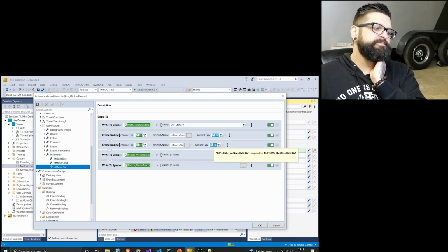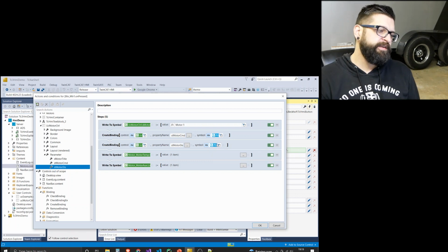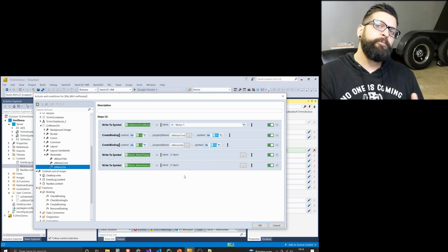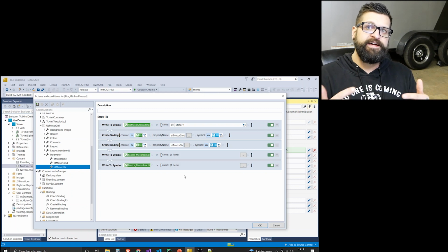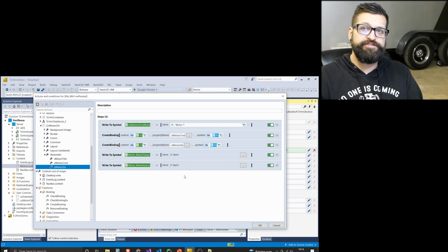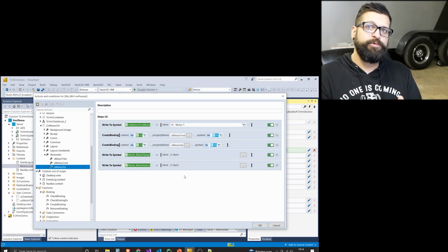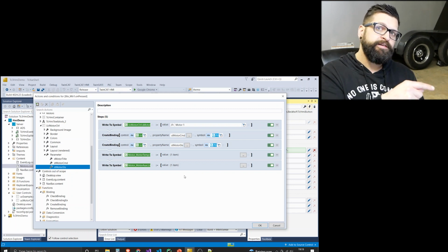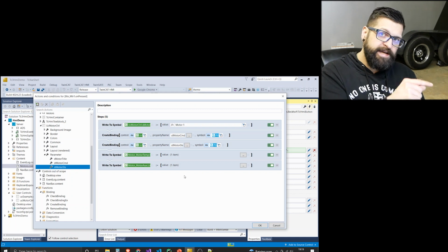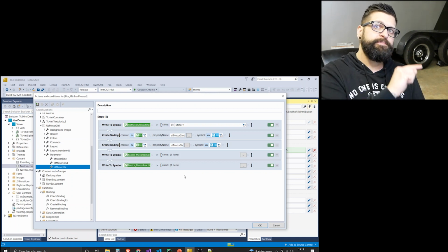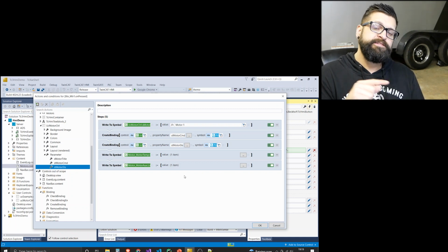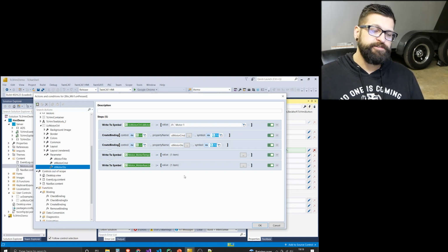Okay, so I know that's convoluted and I apologize for not explaining it well, but that's the difference when you want to create these dynamic objects that have living bindings that go back and forth and they're updated as scan cycles go on. They're not just updated when the event is triggered. So it's not just that I'm passing by value when I click the motor 1 button, but it makes a binding between the HMI and the PLC throughout time until I click another motor button. That's how you do it, is with this create binding function.